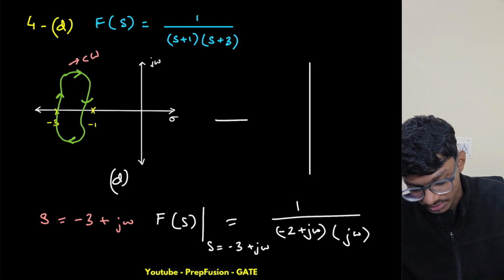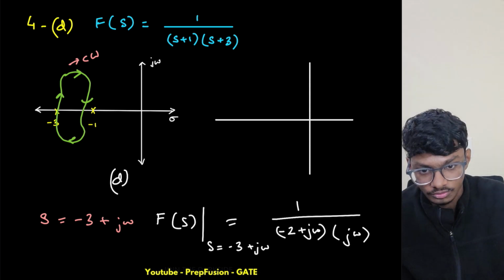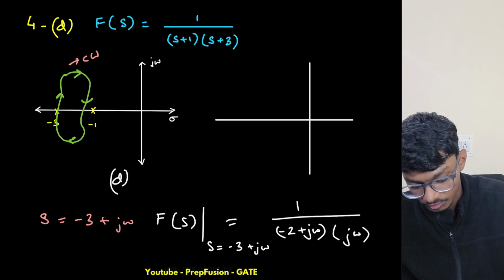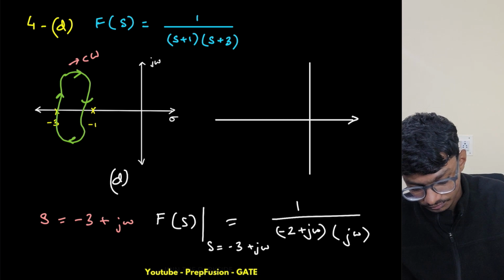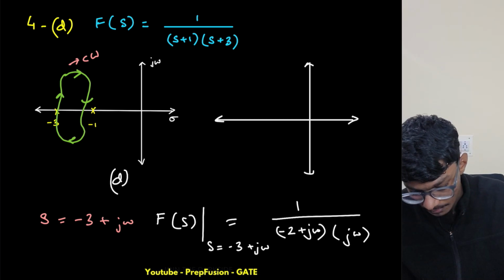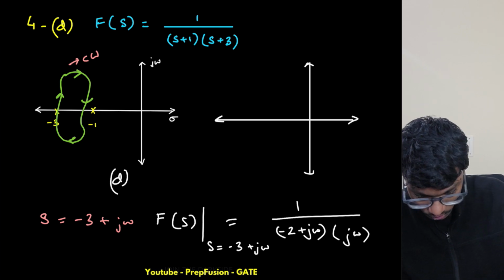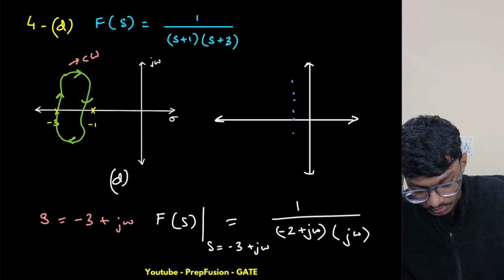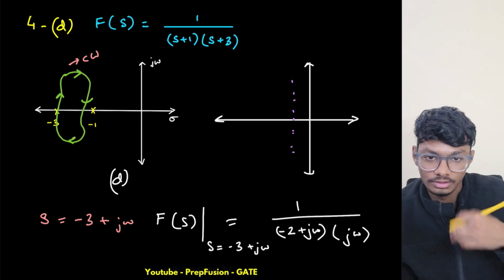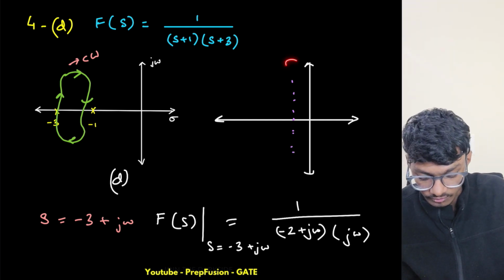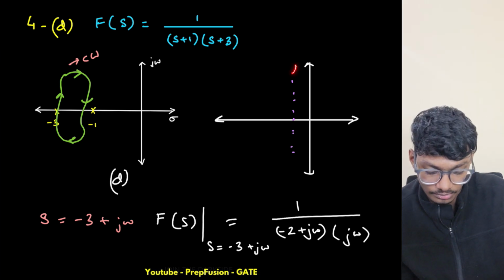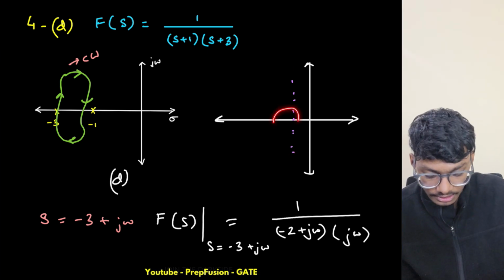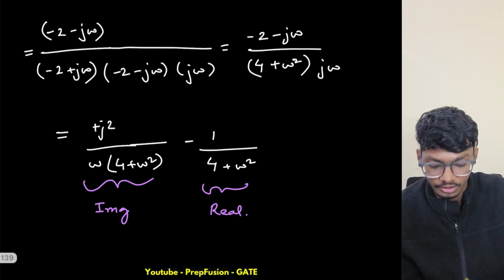plot this one, obviously I won't have the other contour because the other contour is lying outside, so I won't put the other value. So here, what will happen, this is the asymptote basically. If you convert it into angle formula also, you'll see it will almost vary from plus 90 to minus 90 angle, and the real component will lie on the minus 1/4.